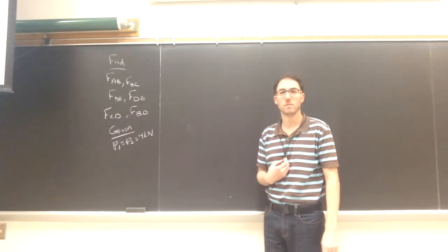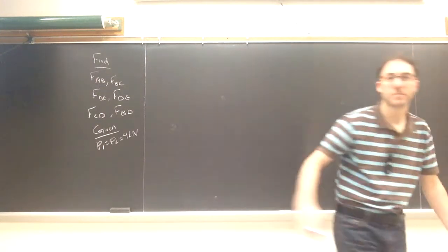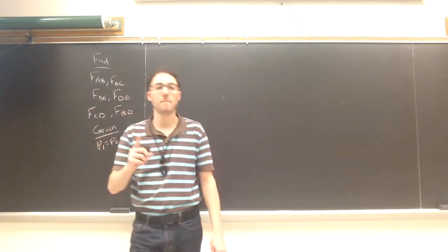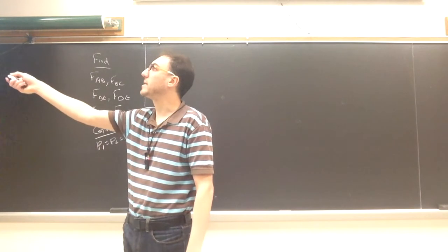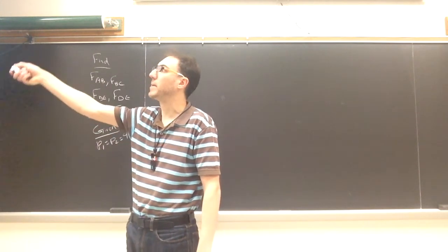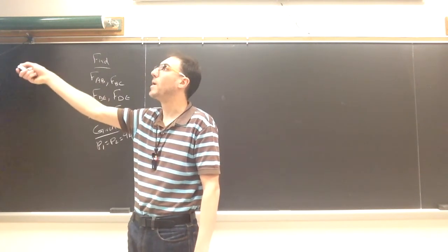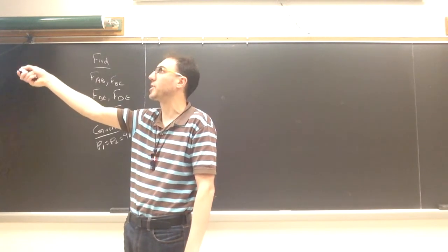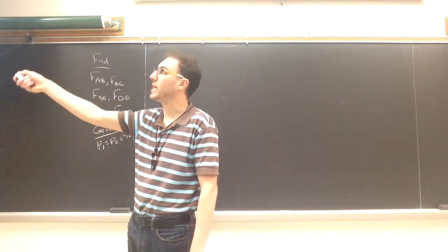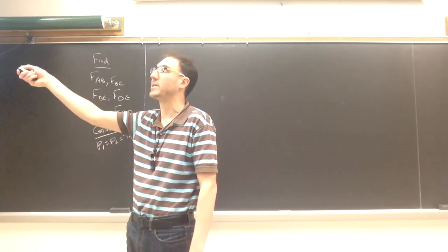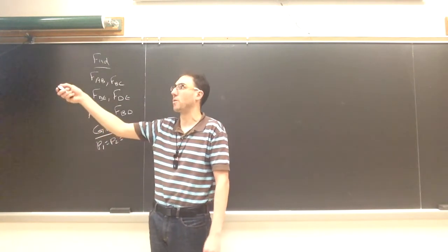Can you explain the second rule for zero force members again? So here we see if it's the only member that has a component in a specific direction. Like here, AB and BC only act along this line. So let's pretend BD were not here. Then anything that has a component perpendicular to this would have to be a zero force member because these are going to cancel each other out along that line, but it can't do anything orthogonal to that line. So if BD did not exist, BE would have to be zero force because it has a component orthogonal to this, and it's the only member that has a component orthogonal to the line AC.